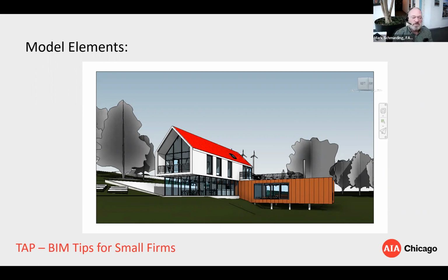Whenever I've been teaching or orienting people to Revit over many years, you always want to think: do I want to do this drafting 2D? Do I want to do this modeling 3D? Or is it some combination of the two? I always act like there's a meter, because sometimes it's not the most efficient thing to model all the time to get every drawing. But it's also not the most efficient thing to draft everything, because you don't get to repurpose stuff.